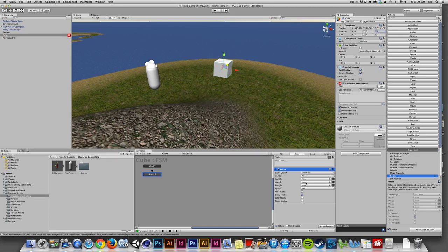Whenever you come across a drop-down menu inside Playmaker, that usually means that it's looking for a value that's based on a variable. We'll talk about variables a little bit later, but I want to hard code a Y angle into this field, and when I click on it, it just says none. If I look over to the right, there's this little gray button, and if I click on that, that switches between using a hard value or using a variable. So I'll turn that toggle button off, and now you can see that I have a Y angle of 0, and I'm going to change that value to, let's say, 90. And what that's going to do is rotate this cube 90 degrees, and I'll select this per second option down here every time the frame refreshes.